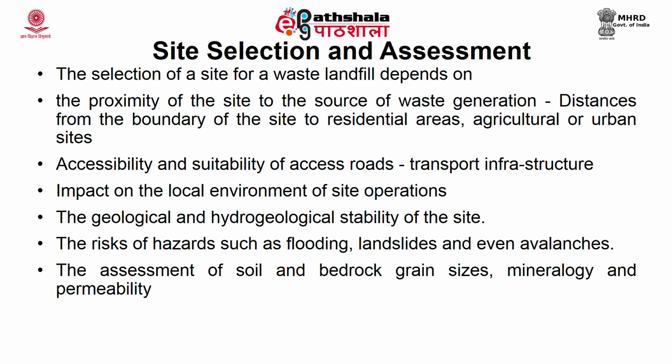Now, the assessment of soil characteristics is very important, because the leachate gets percolated only through the soil. So, you also have to focus on the soil characteristics. You should know the mineralogy and the permeability of the soil. You should also find the grain size of the bedrock.